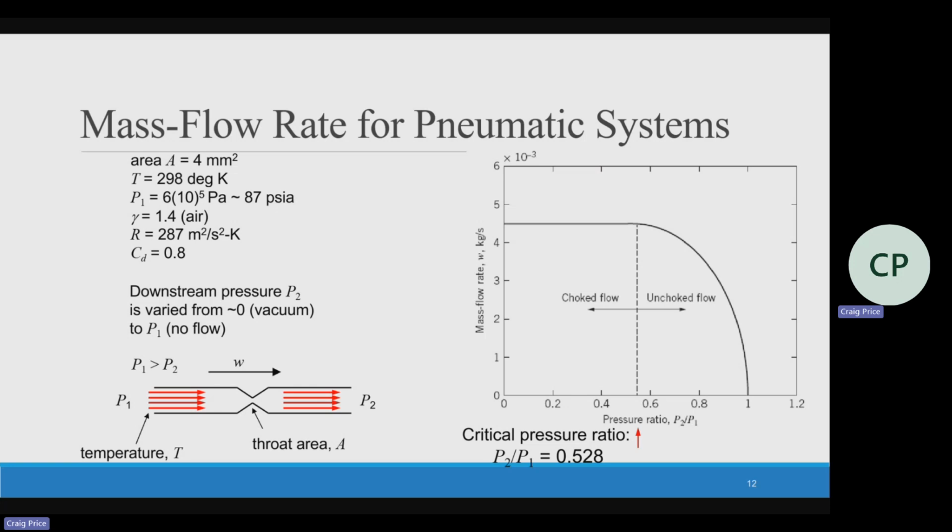At first, it's going to look like this: we're going to have a nice constant flow rate from upstream to downstream pressure. But as the pressure in the bottle grows, there's a point where there's not that much of a difference, and so our flow rate becomes nonlinear. It's not as nice. It's swirly. It doesn't want to really push through because there's not that much of a difference. Ultimately, there's a point where they're equal. Once that water bottle's filled with air, it's all the same pressure and there's no more flow. That's really what this graph is showing.